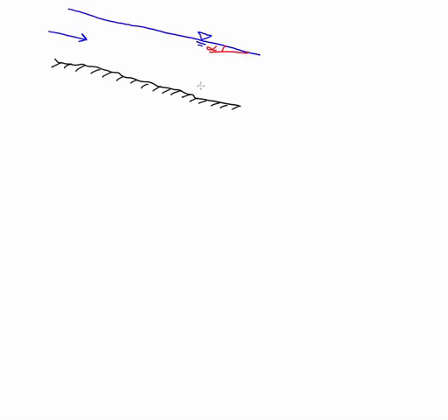What we're interested in, recall, is finding the force that's acting to erode the bed, which we call the boundary shear stress, tau naught. So that's the force that we're trying to find, and what controls that force. Now that's a stress, so that's applied over an area. Force applied over an area is called a stress. So we have to think, what are the properties of the water? Slightly different way of thinking about this.